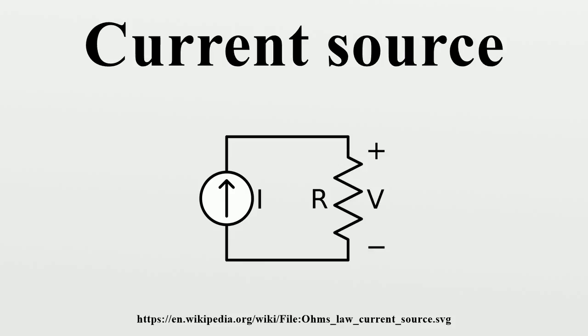Current stable nonlinear implementation. They are implemented by active electronic components having current stable nonlinear output characteristic. When driven by steady input quantity, these circuits behave as dynamic resistors, changing their present resistance to compensate current variations. For example, if the load increases its resistance, the transistor decreases its present output resistance to keep up a constant total resistance in the circuit. Active current sources have many important applications in electronic circuits.